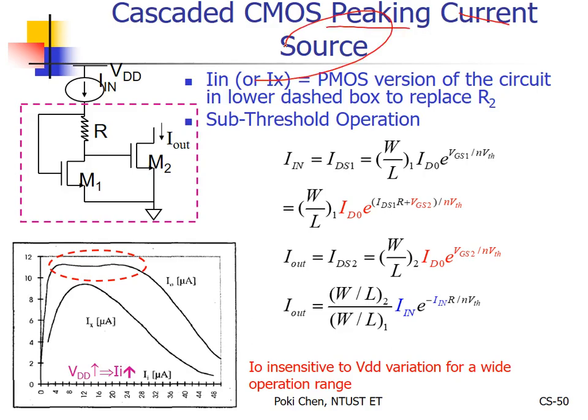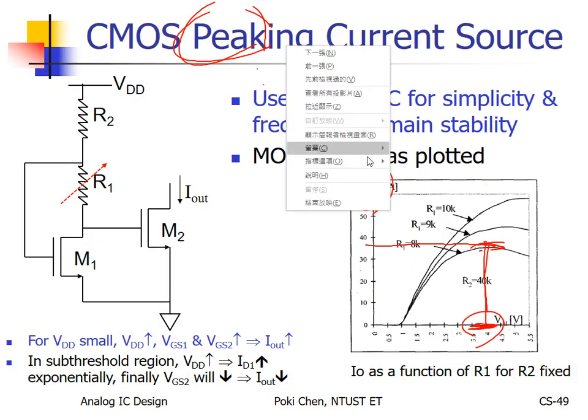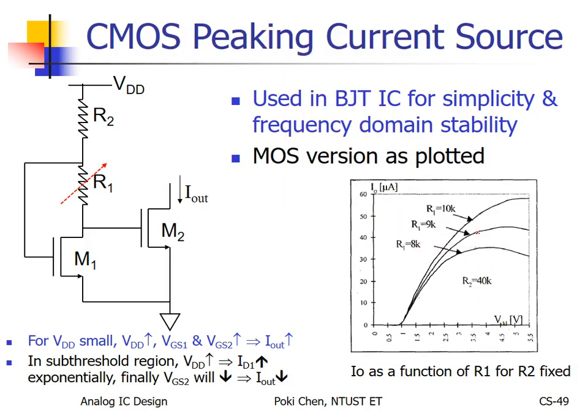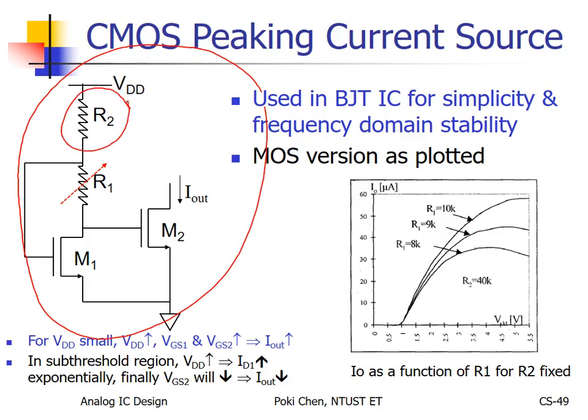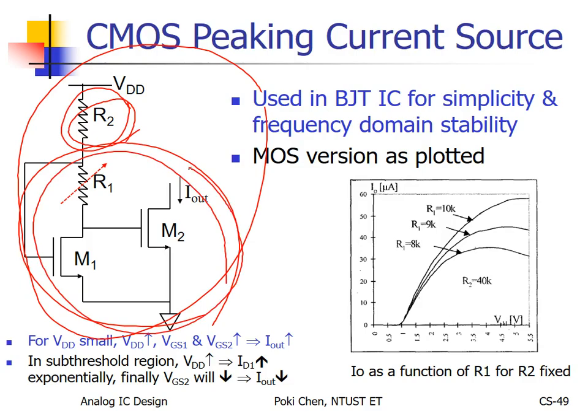double peaking. Okay? You can see here, if you have a patent for this, how can I break through your patent? I change this. With what? The other one. Okay? We replace R2 with the other counterpart circuit. What is the definition of counterpart circuit? I told you already. Flip it upside down anyway. Then change VDD to ground, NMOS to PMOS, blah, blah, blah.